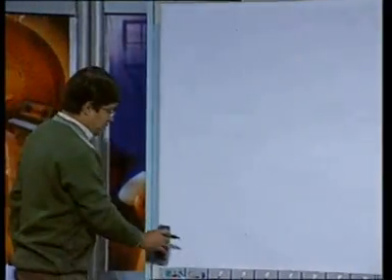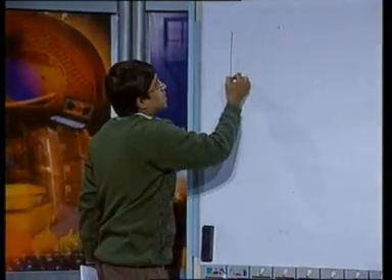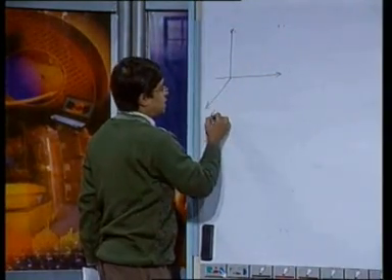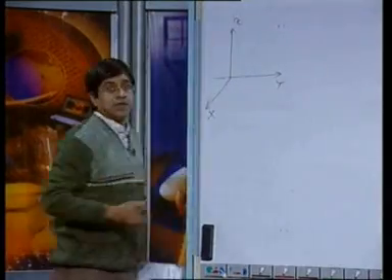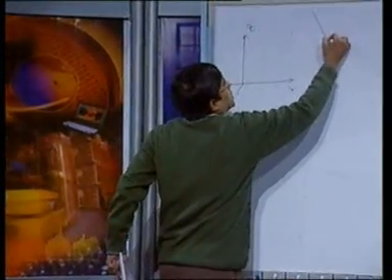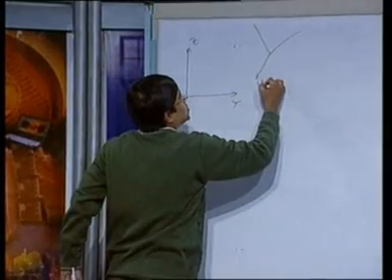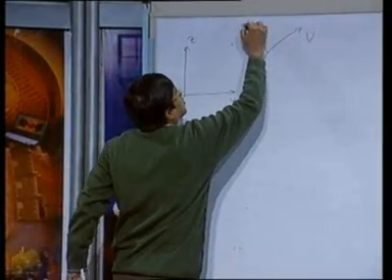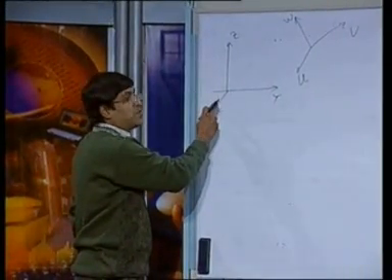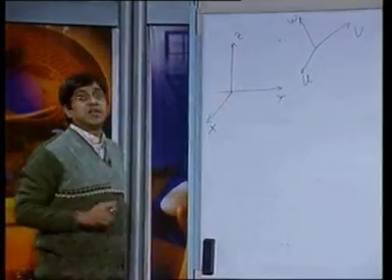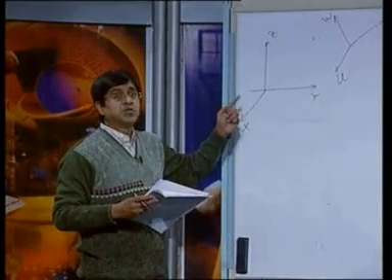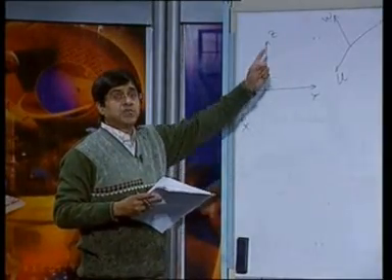For example, I have a fixed coordinate frame, say x, y and z. And now, I want to represent here say u, v and w. So, this is my fixed, that is my moving one. What I do is I can reach from this orientation to that orientation through a series of rotations. Since it has 3 degrees of freedom, with 3 rotations I should be able to reach there.